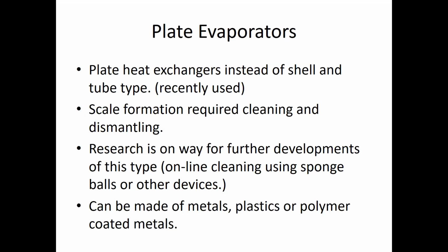And the nanotechnology has played a significant role here, that you are trying to coat your materials, your pipes, with a nano size coating. The size is too small. It does not reduce the overall heat transfer coefficient on one hand. On the other hand, it's a very smooth surface so that the salt will not precipitate, but it will slide over the surface and leave. And accordingly, you have a longer life between two shutdowns of the units. And that improves what we call the plant factor, that the factory is going to operate more period of time producing and you don't have to shut it down.